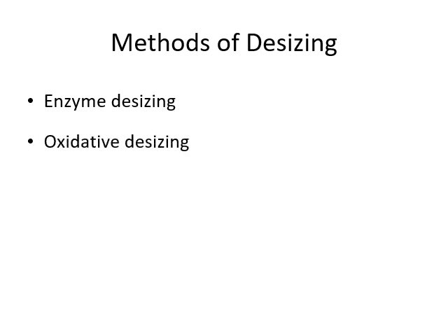Another method of desizing is oxidative desizing, where sodium hypochlorite or hydrogen peroxide is used. Cellulose is a part of starch material and also a part of the fiber. Because of the very low degree of polymerization of these size materials, they degrade immediately due to these oxidizing agents, and decomposition of the starch takes place. There is a very minor effect on the fabric, meaning the cellulose present in the actual cotton fiber.